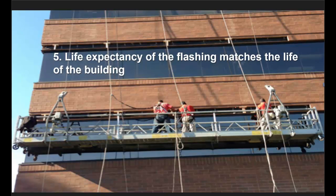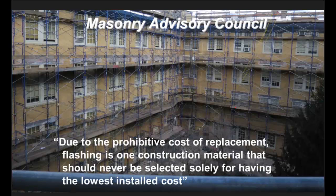Number five brings us to the life expectancy of the flashing should match the life of the building. If you're building something with masonry, chances are it's going to be there at least 20 years. Most people I talk to, masonry buildings, we're talking 50 to 100 years. You don't want to choose flashing that is just the cheapest product out there, because replacing flashing is extremely expensive. It's a labor-intensive process. In the Maryland, D.C., Virginia area, it's about $300 to $400 a lineal foot.